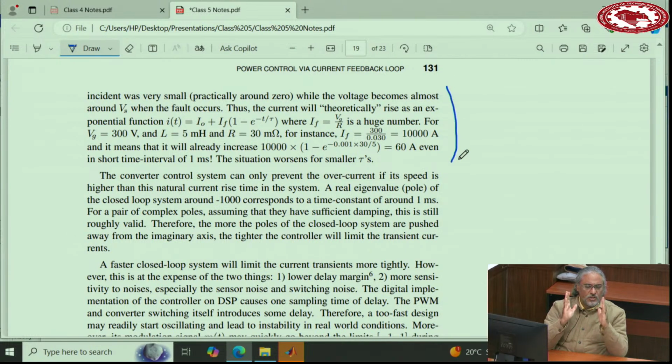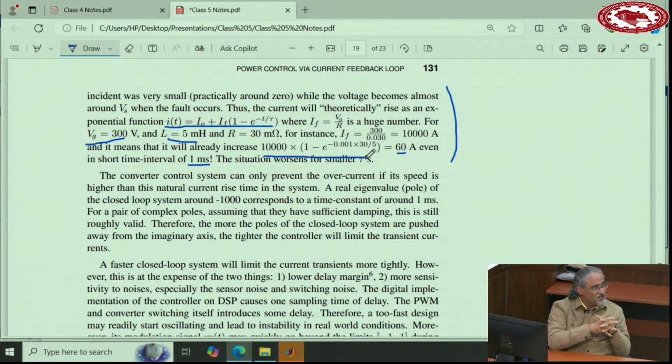Let's say the converter is operating in normal condition connected to the grid, right? So this is the grid and this is the converter, the voltage of the converter. So these voltages are very close to each other and the current is flowing. These voltages are very close to each other because the resistance is small. Now let's say this grid voltage instantaneously or transiently drops, because we cannot really make it fast. Right? One solution is you need to increase the switching frequency to 10 kilohertz. If you increase it to 10 kilohertz, probably you can address this one.